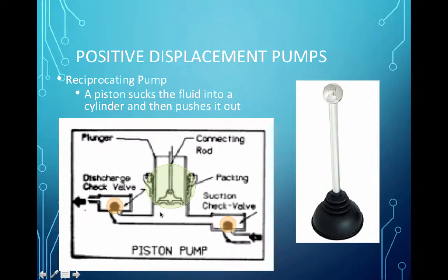Reciprocating pump: your automotive engine is sort of a reciprocating pump working backwards. It has this volume right here in the cylinder, and as the piston moves up, the volume changes, and so now the volume is much bigger. As it's moving up, water's going that way. It lifts this check valve. It's trying to pull water back this way, but that check valve prevents it from coming back.